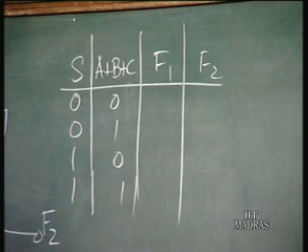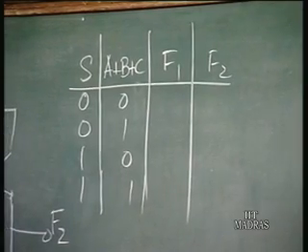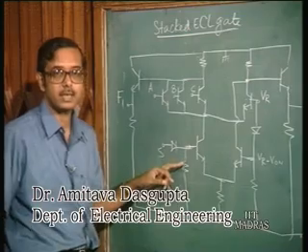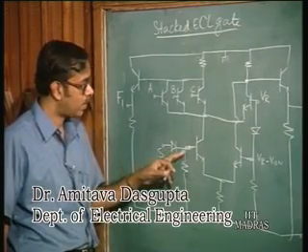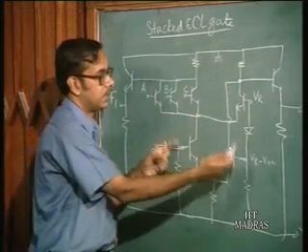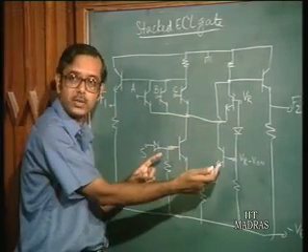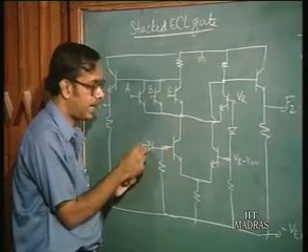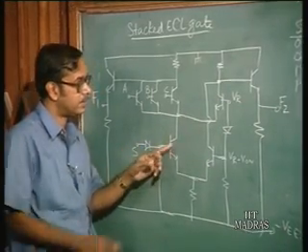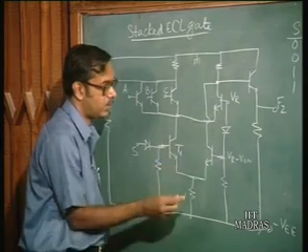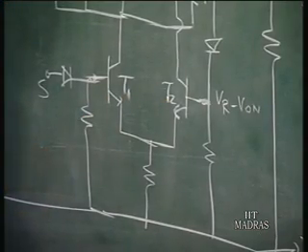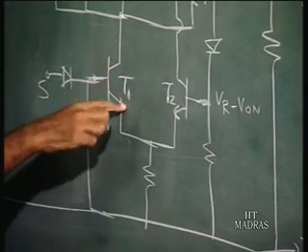Now, if you look at this emitter coupled structure, the lower part of this stack, the voltages on this side are just level shifted down by one diode drop. Now, if S is high compared to VR, then the current flows in transistor T1, and T2 is off. So current flows in T1 and T2 is off.